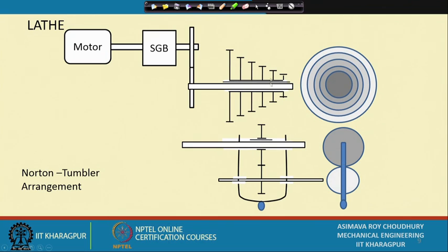These gears are shown in this view, and this one comes and I attach it. So, even though the center distance of this gear and that gear and these gears are not going to allow direct connection, I have an intermediate gear by the help of which I am connecting up these gears. This is the Norton Tumbler Set. So, the calculations that we have done, 56 by 24, 44 by 24, all these things become realities. Okay. So, let us see further.